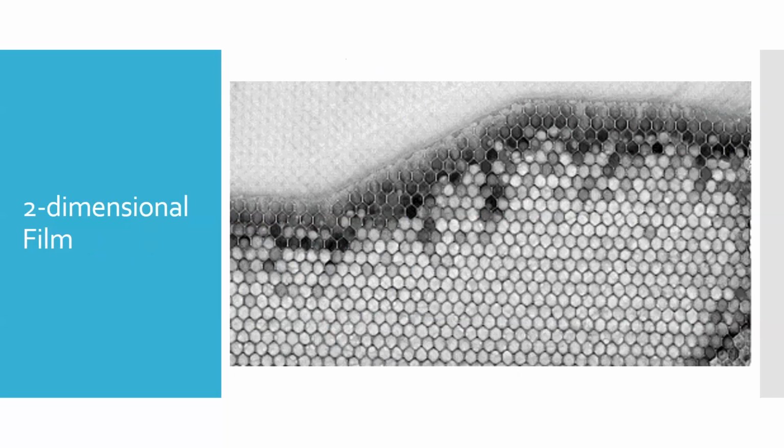In this case, remember, white is where the radiation doesn't pass as easily. And so what you're seeing here is there's thinner layers of epoxy in this area. The radiation actually passes through the honeycomb and the fiberglass and the resin in different amounts. And so you can see those differences.